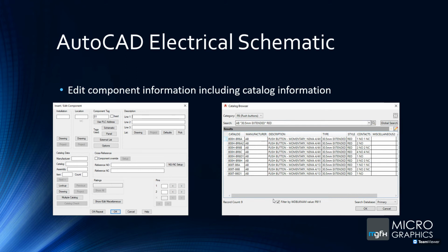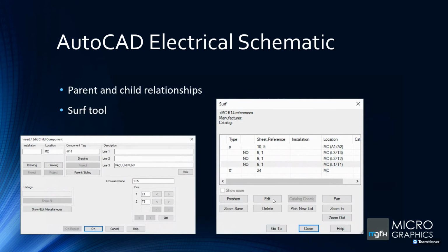And the way AutoCAD Electrical works with that one is, if you put in too many, so maybe I've got 5 normally open contacts, it'll give you an error and say, sorry, but you actually can't do this. You look on the left-hand side, you'll see the reference number. When I say reference, normally open, normally closed, it'll tell you what you've actually got involved in there. Okay, so moving on to that.